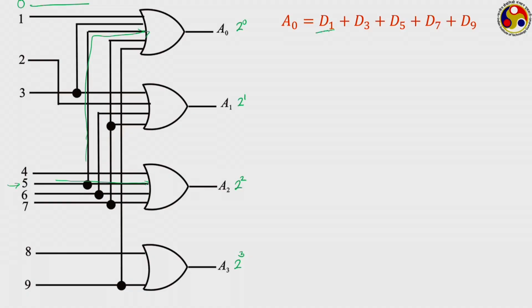Whenever you are pressing 1, it is switching on that line, and an electrical signal is going in the form of this D1, and accordingly it is being activated as this A0 switch, and it is giving a 1 in the least significant bit, in the A0 position. But follow this 1, it is connected only to this A0 because you need other 3 bits to be 0. So, you are having this 0001 in the 4-bit register.